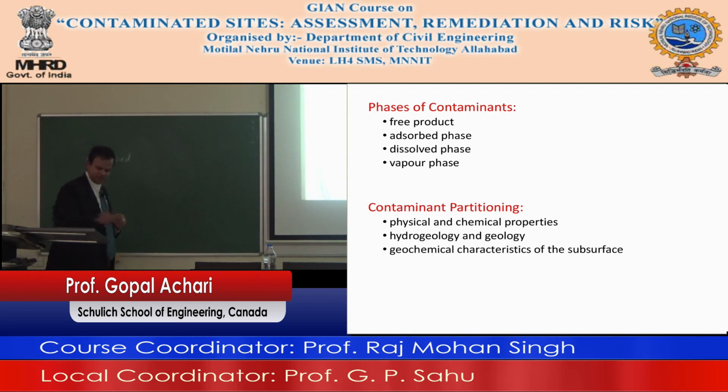There is also a dissolved phase. You have the soil particle, I shouldn't say sand, because it can be any one. You will have the adsorbed phase, but if there is water in the pore, it will be dissolved in the water. It can be in vapor phase in that pore space.